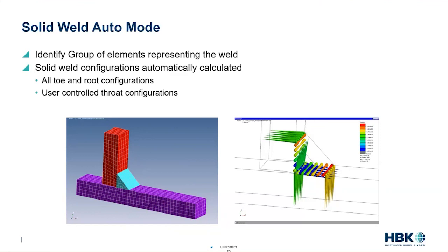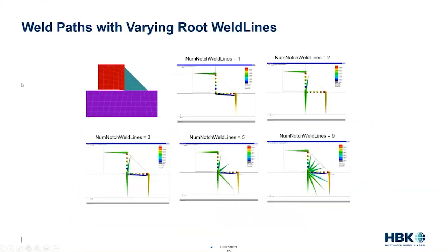And so there's actually an additional parameter that goes with this, where we can control how many paths come out of this root section across our weld geometry. Let's go down to the bottom one here for 3. The starting point I would use would be 3. 3 would give me a weld failure location going forward from the weld root and looking at peeling the weld off of the vertical plate.